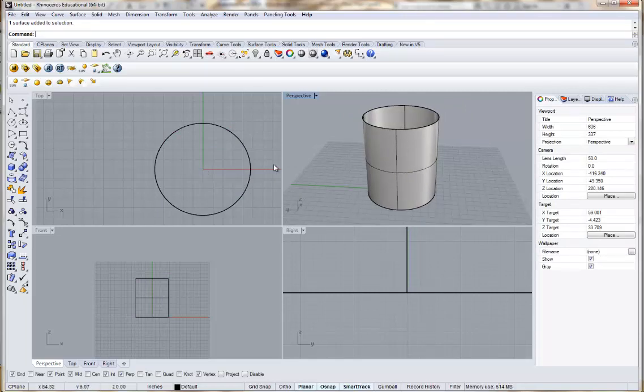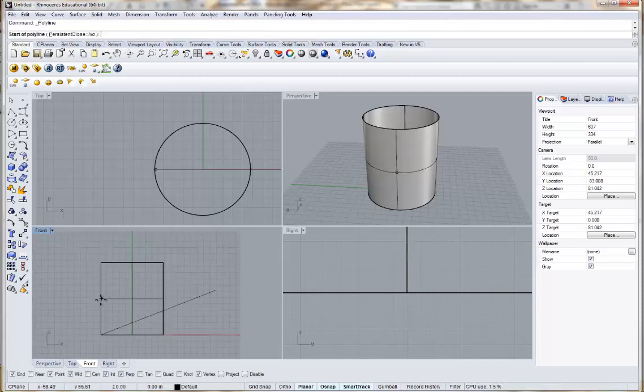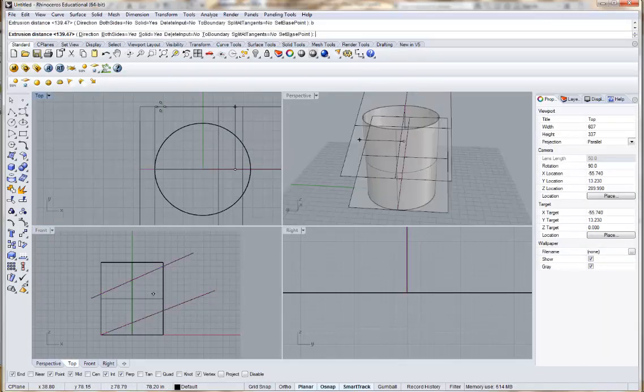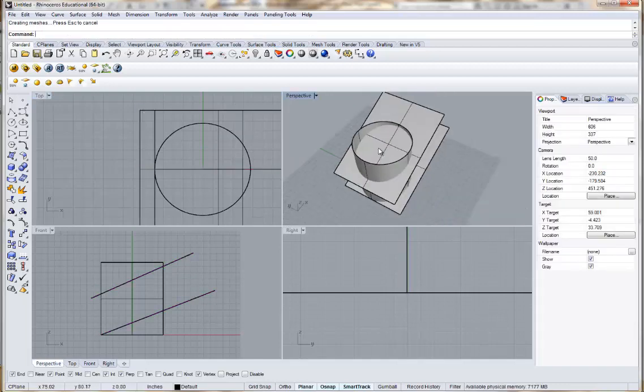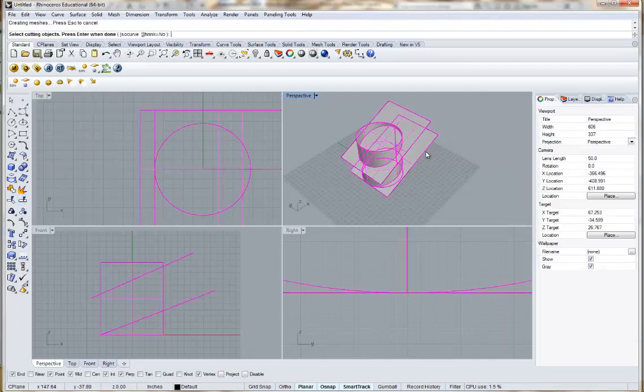I assume that when you're doing this, you'll set the radius and know what you want to do, and you'll see how this works in terms of being really precise about where you want to set that geometry. So assuming that we have developed this, let's carve a chunk of this away so we can do part of that. I'm just going to eyeball this here, and you will obviously be much more precise. So I extrude this, and in this instance I'll do both sides. I'm going to take this and split it with each one of these.